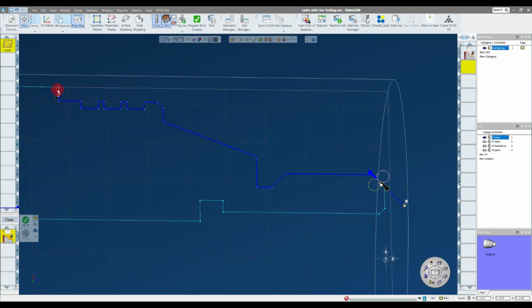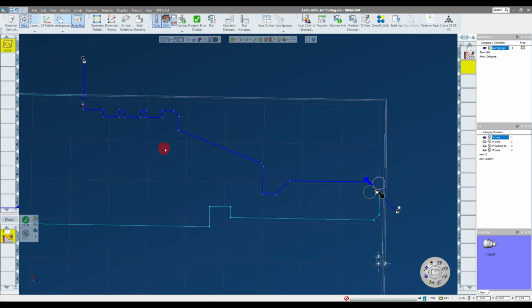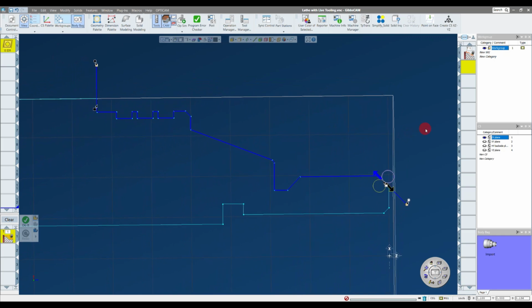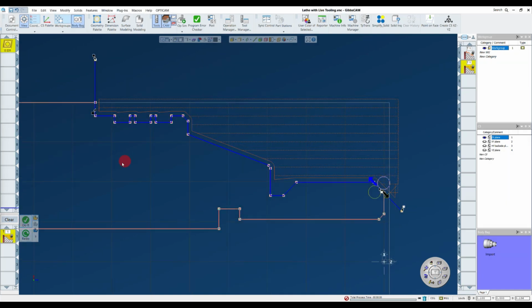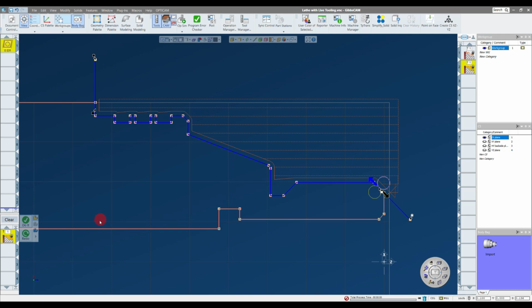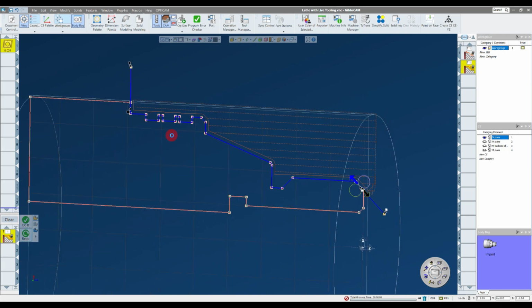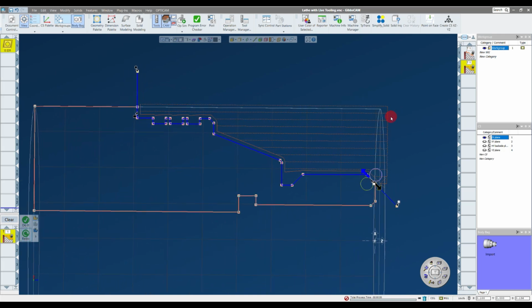And then I'm simply going to drag my toolpath extension, my black circle, outside of my material. So my marker setup kind of looks like this. And if I click Do It, there's my toolpath. Now you'll notice the toolpath ignores my toolpath extensions from my white and black circle markers. If I click Redo, it just simply creates toolpath where it knows that there's material.